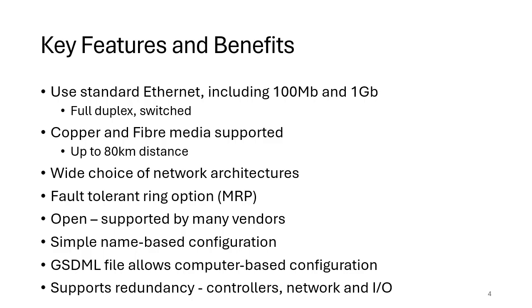And what helps there is, on the Ethernet side, the main PROFINET standards include quality of service, so in theory they have a higher priority on the network. Of course, ultimately it's going to depend on your network bandwidth, so there's a degree of architectural support there that you might need to consider. But generally it does mean that you can just have a single Ethernet network and you can put all of your devices on it and there's no issues about them all working together.